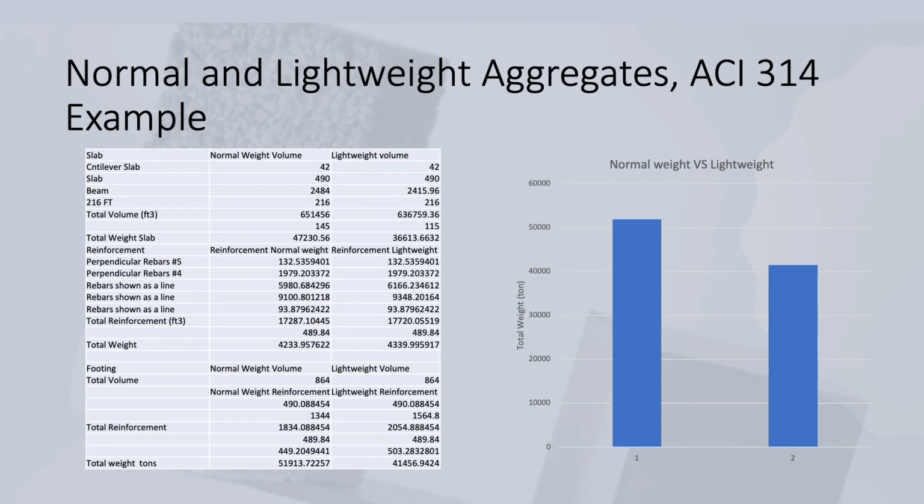As you can see, the total weight of the lightweight concrete is approximately 20% less than normal weight, which can reduce the dead load of the structure and provide more open space for the architect and structural designer. Also, the results include an evaluation of current strength values and provide recommendations to enhance the reliability of design codes for structural lightweight concrete.